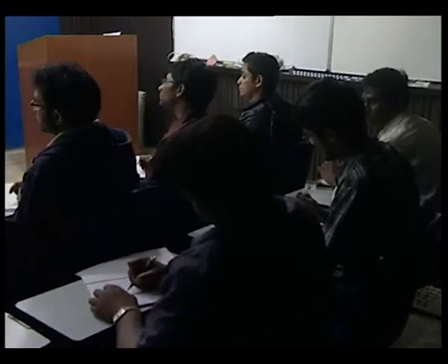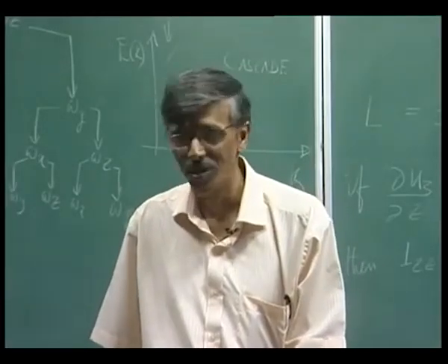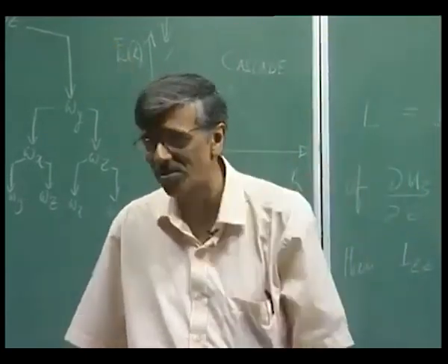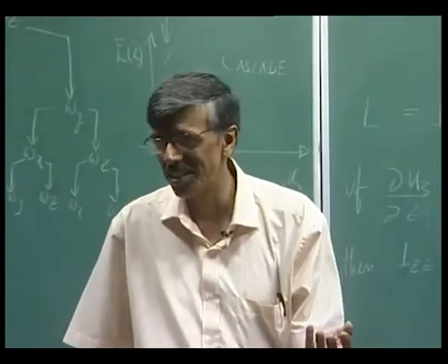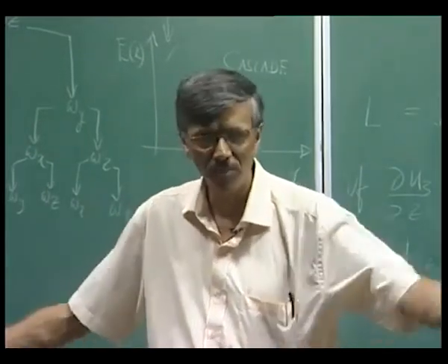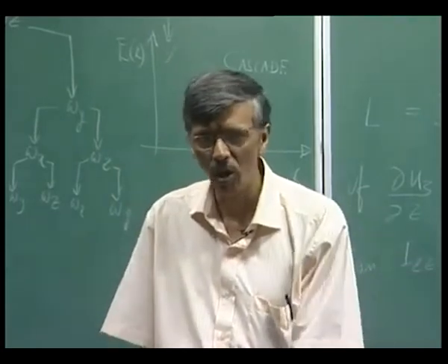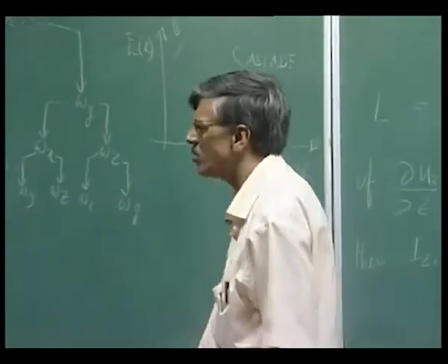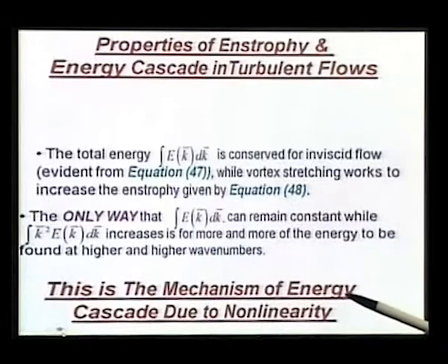Then we have also seen bypass transition effects. What did we see? That if a single vortex is simply moving at a constant speed, there is no trace of any unsteadiness. But what happens down below in the boundary layer? We get vortices erupting all over the no slip boundary, and that is a very high wide band phenomenon. So, there are some things, but please do understand that for 3D flows at least vortex stretching helps you explain how energy is transported from low k to high k.